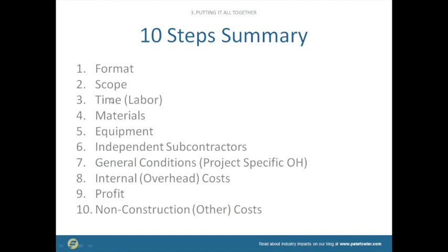So then there's the time, the labor, and materials that we're using. What equipment are we using? What subcontractors are we using? And ultimately, some people think that there's really like some black box, that you can't understand where these numbers come from. Well, if I'm hiring a subcontractor and I get numbers that I think are wacky, I literally sit down and estimate what I think they're going to cost, and I begin negotiating with them and say, what are you talking about? And it's the same thing when we get a change order.